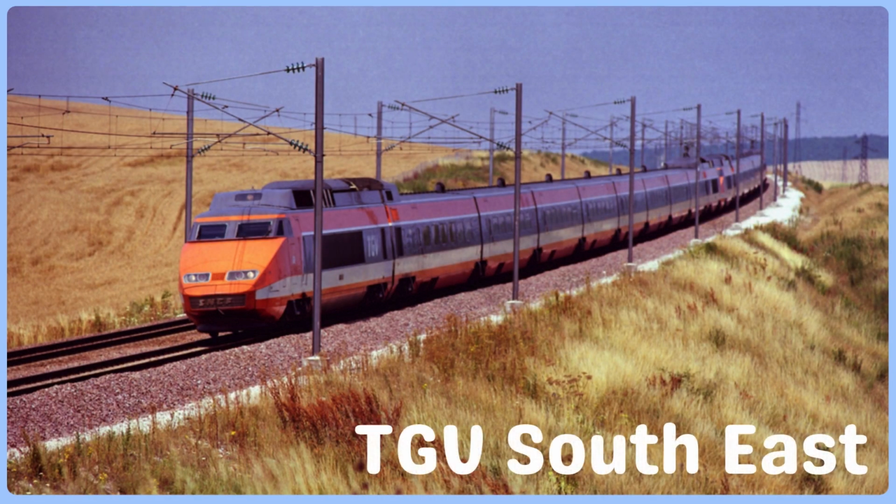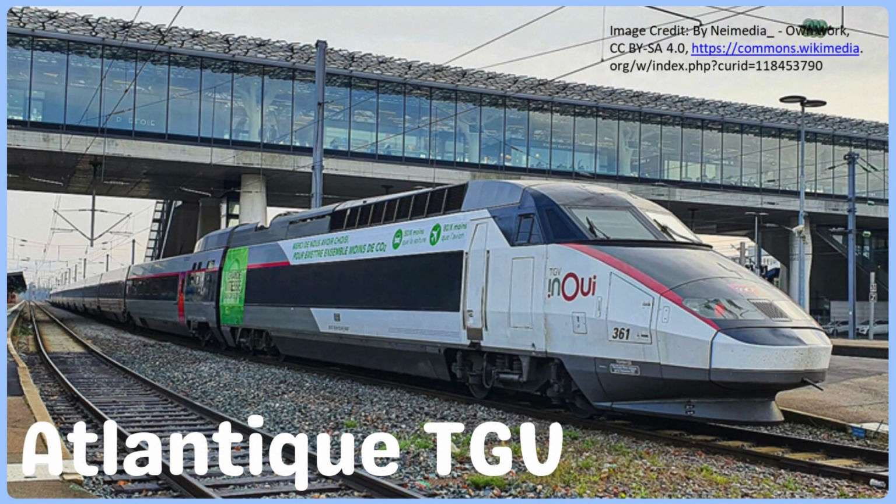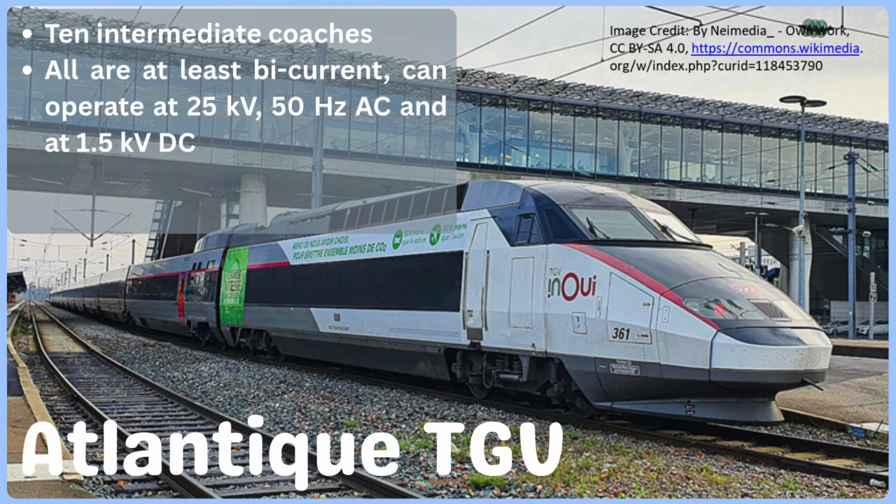This is TGV Southeast. The Atlantic TGV rolling stock marks significant technical progress in terms of performance. It uses 10 intermediate coaches between the 2 powerheads. All Atlantic TGVs are at least bicurrent, can operate at 25 kV 50 Hz AC and at 1.5 kV DC. TGVs have 2 pairs of pantographs, 2 for AC use and 2 for DC.